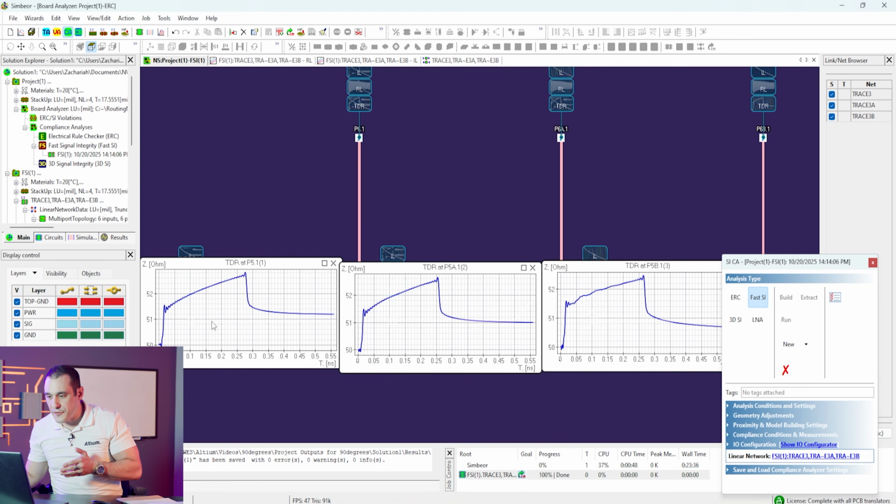You can see here that the final impedance at the end of this is only about 0.2 to 0.4 ohms difference. Not a very big difference if you consider what the myth says about right angle routing, which is that you should encounter a brick wall impedance and get these huge reflections that totally destroy signal integrity.